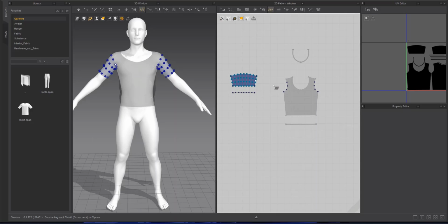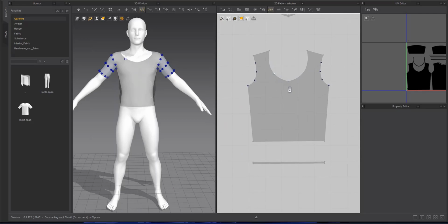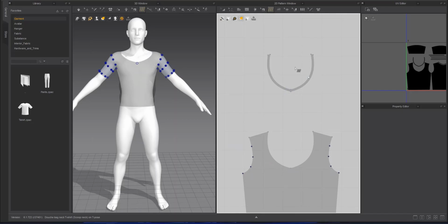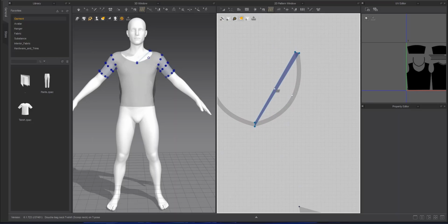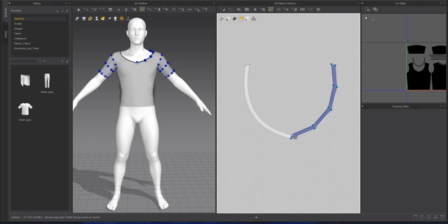Select the single object mode and choose one of the 3 modes: thin weld, thin unweld, and thick, based on our needs. Thick mode in thick parts: its UV is not defined. So in the case of thick output, it is better to define UV thickness separately for other parts in that software. UV is applied to this output, but it is not set as UDIM, and we need to identify each of the UVs and define it as a poly group so that we can create material on each of the UVs separately.